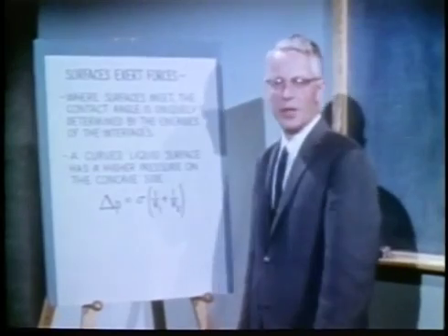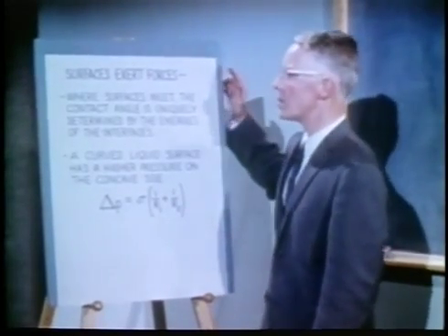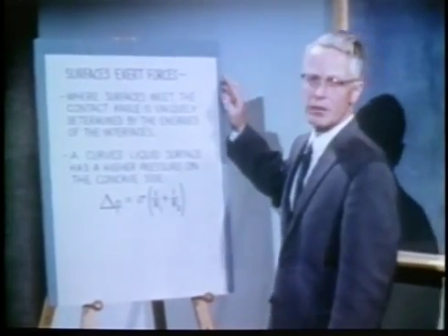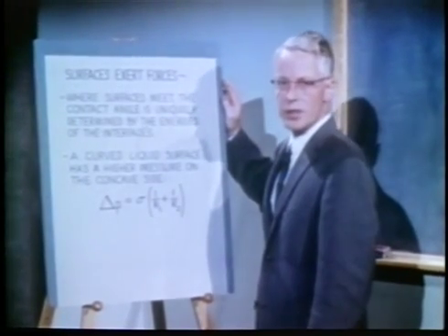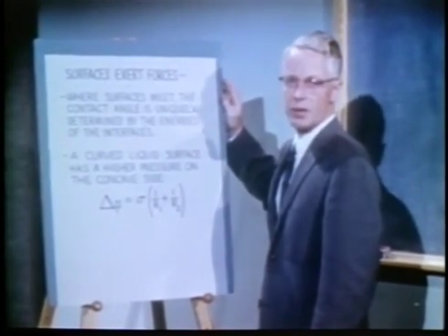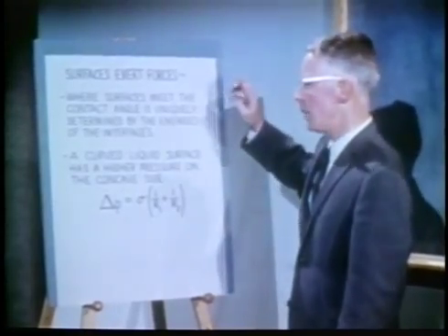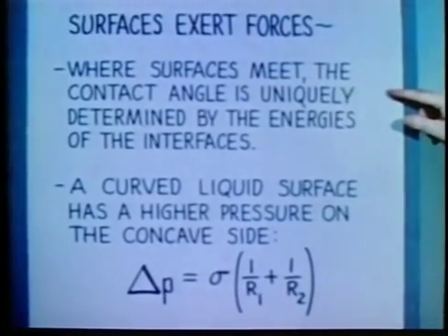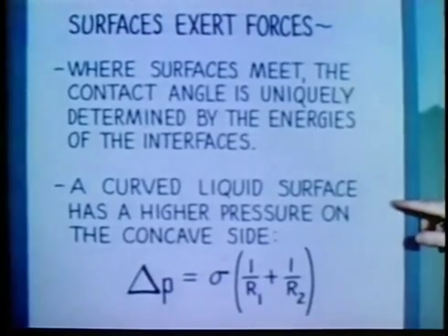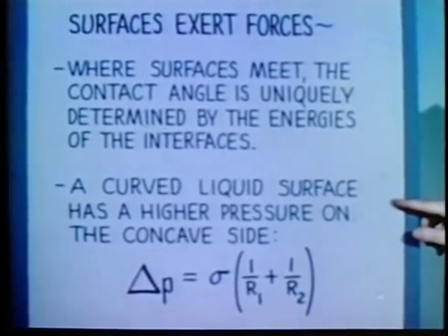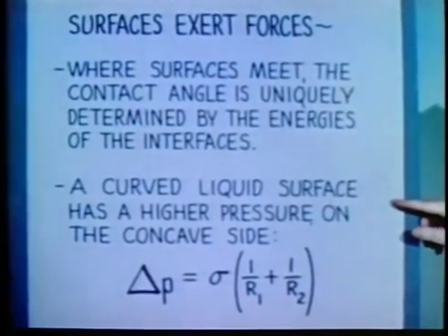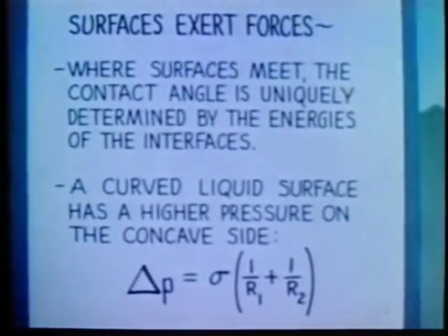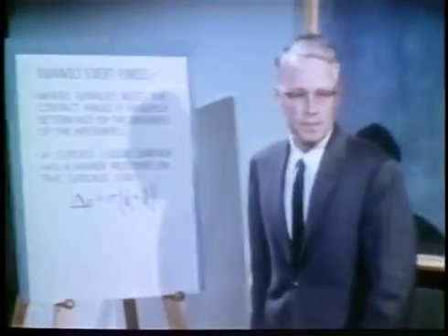If we accept this hypothesis that surfaces exert forces, we find that there are three boundary conditions expressing these forces that need to be used with the continuum equations of fluid mechanics. We've just seen examples of the first, that where surfaces meet, the contact angle is uniquely determined by the energies of the interfaces. The second boundary condition comes from a force balance across surfaces. One finds that a curved liquid surface has a higher pressure on the concave side. For example,